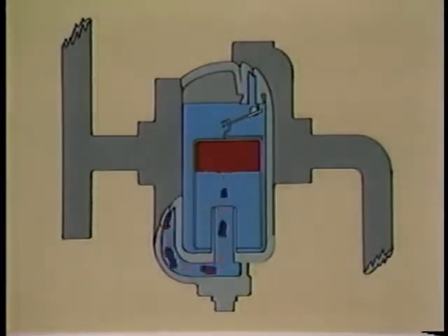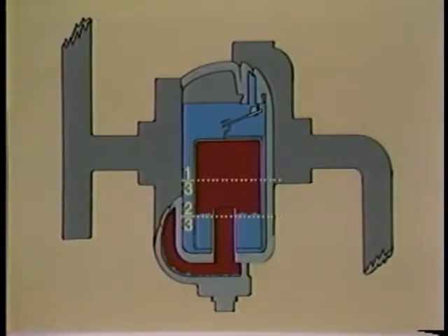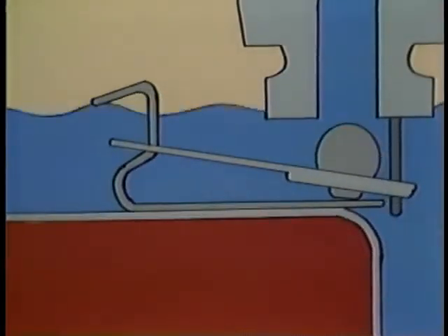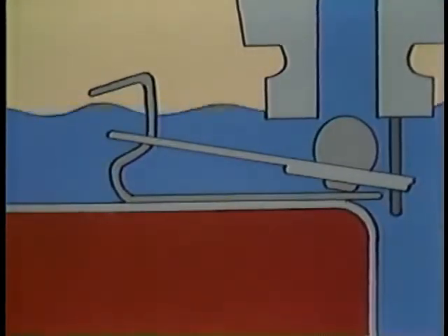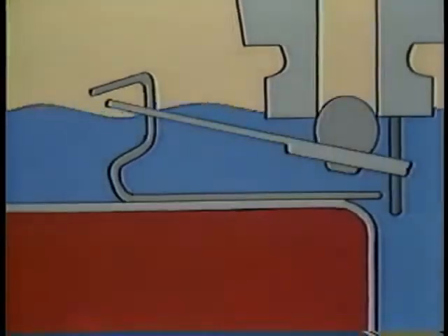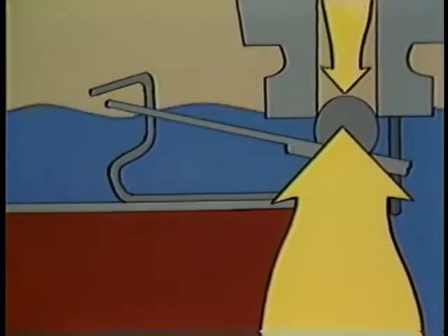When approximately 2/3 of the volume of the bucket is filled with steam, the bucket becomes buoyant and floats to a point where the valve is pushed toward the orifice by the bucket clip extension. The higher condensate velocity near the orifice propels the valve into the seat, where it is sealed and held shut by differential pressure.